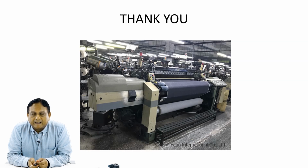So these are the different aspects of shuttle looms and shuttle-less looms, and the different motions employed in weaving are almost similar in the shuttle loom and the shuttle-less looms. Only the way of carrying the weft yarn through the shed is different. The shuttle loom carries the weft thread through the shuttle, the projectile loom carries the weft thread through some gripper or projectile arrangement.